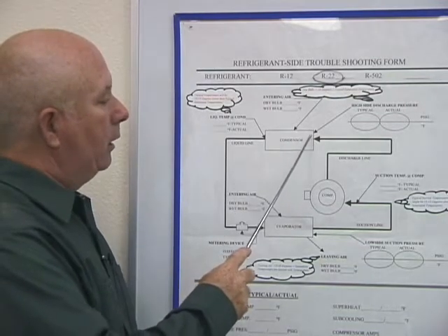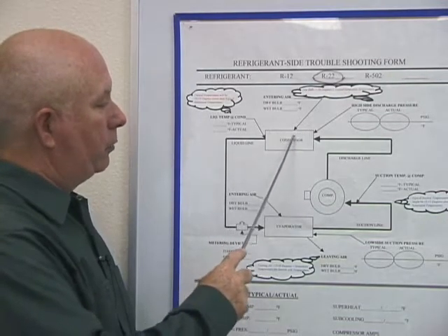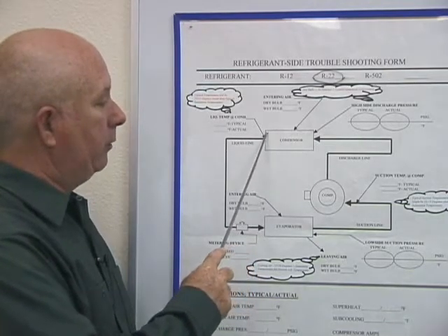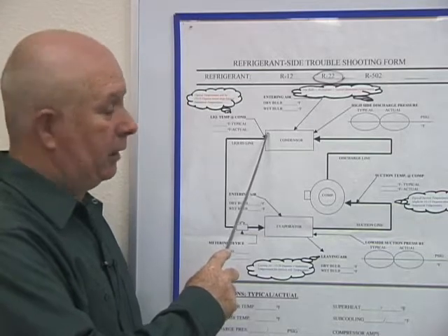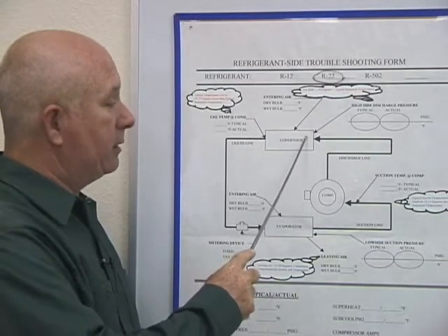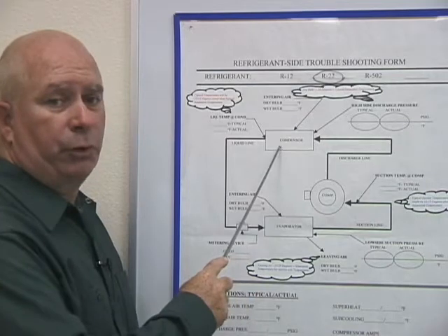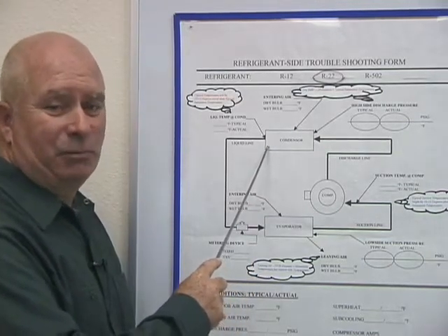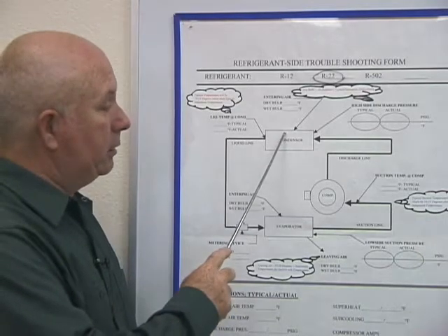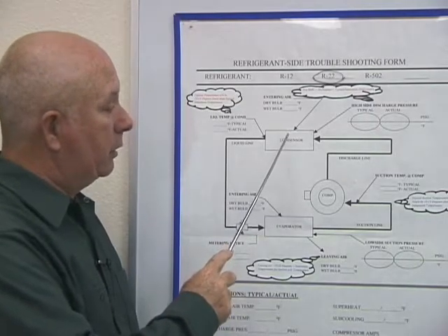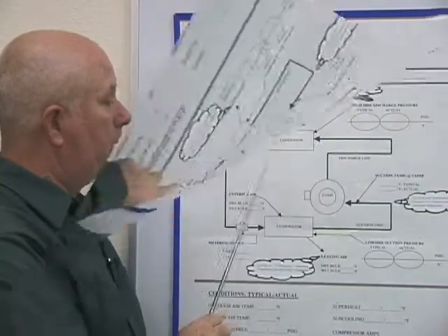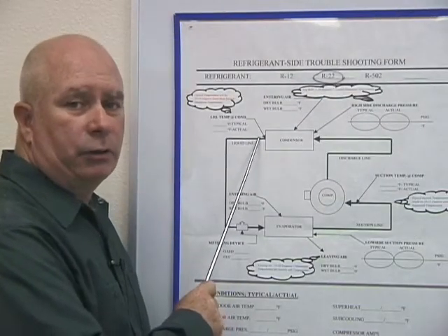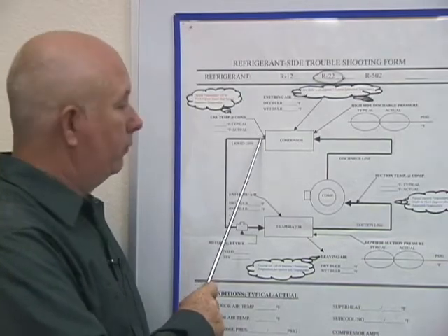So hopefully, as this refrigerant flows through your condenser, remember it is desuperheating because it's a superheated gas at this time. It's starting to condense somewhere down through this condenser, and we don't care. And then eventually it's going to come out as a subcooled liquid. So the three things that go on is desuperheats, condenses, subcools. It comes out as a high temperature, high pressure, subcooled liquid.